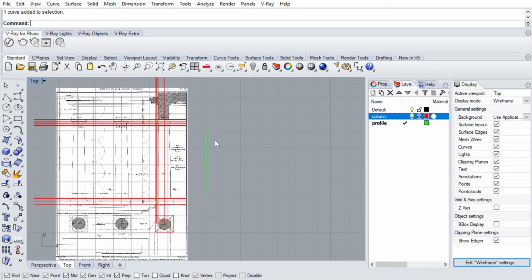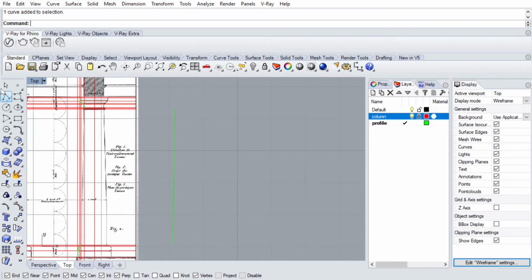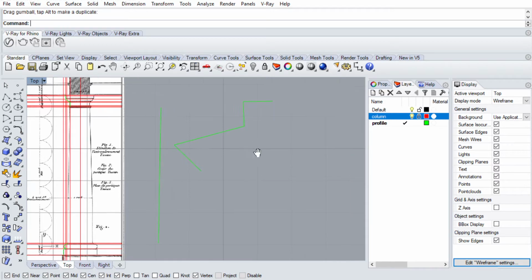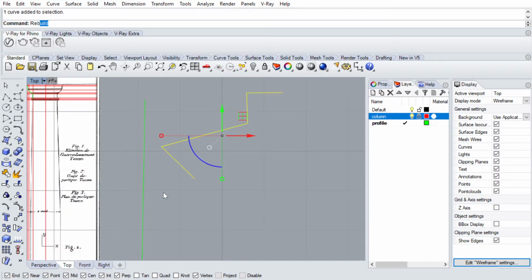Let's go over some of the curve tools first. When we draft a polyline, we basically can visualize the corner points using the points on command here. So this will give me the points, and to visualize these arrows, you can turn on the gumball, and you can move the points anywhere you want. Now, if you want to change the degree of this curve, we can rebuild it. Now it has 5 control points, but it's a degree of 1, and the degree means the way the data is interpolated between the points, so to draw the curve.